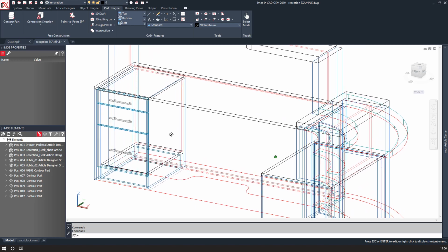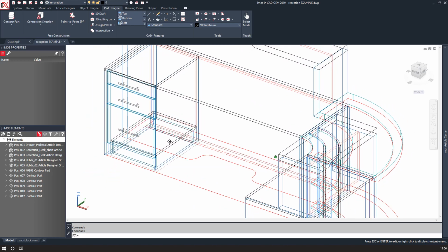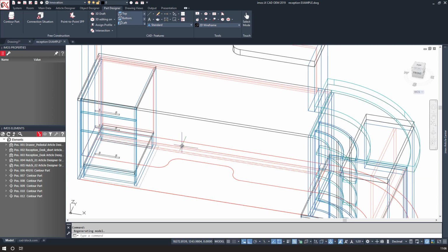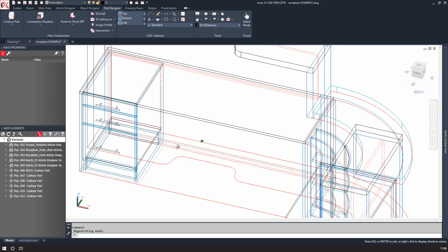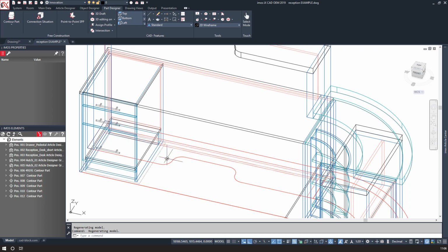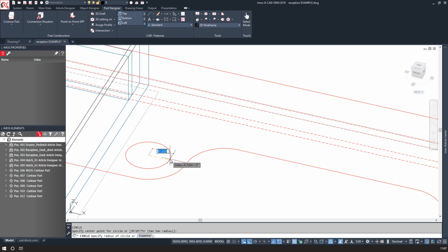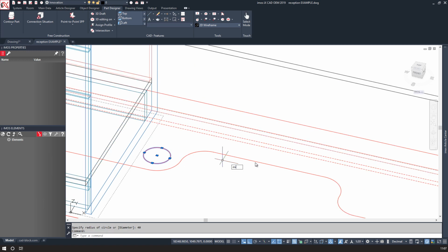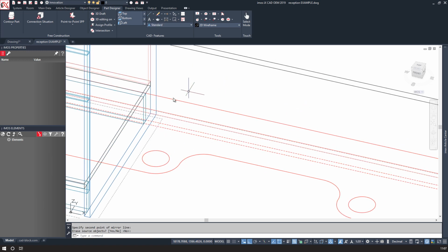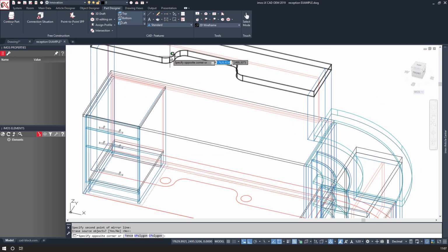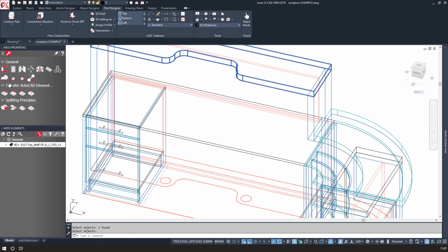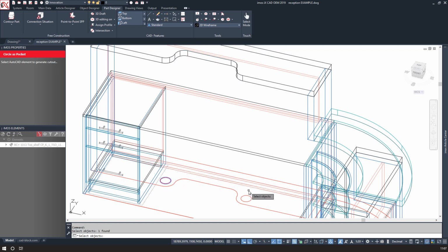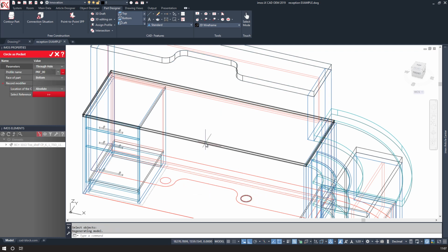We can again use AutoCAD circles or polylines and then transfer this as machining to the individual pieces. Unlike traditional 3D modeling, where we could use a cylinder shape that's extruded and then used to subtract away a piece of material, what we do here is use imos commands such as circle to pocket, which I'll use in this case on the top piece, and that will then identify these features as machining elements, which then need to be passed to the CNC machine later on in the process.